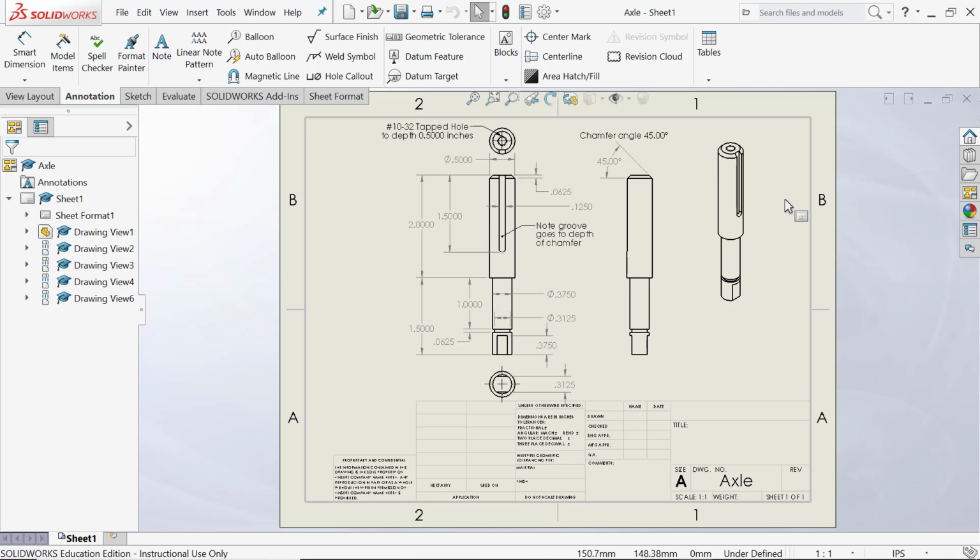All right, the center should be on the origin, but what plane should we put our first sketch on? On the top plane makes sense to me. Yeah, if you think about it oriented this way, if we draw a circle for this top cylinder on that top plane and extrude straight up, that'll also mean that our right plane will come through it sort of this direction, and our front plane will come through it sort of this direction.